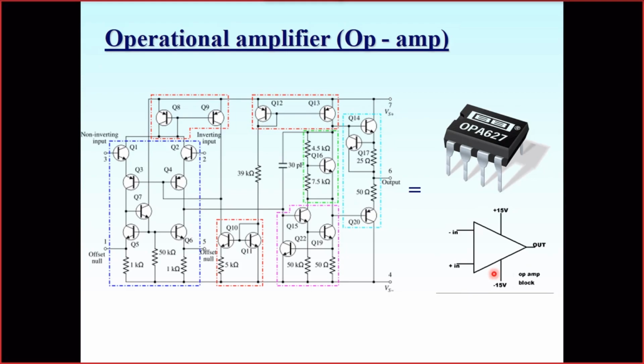Nevertheless, if you are designing an assembly circuit or drawing that you are going to use afterward to drive PCB design software, then of course you have to indicate what happens at every leg of the chip. In a principal circuit, when you just draw it to explain how the device works, these power supply lines may be omitted.